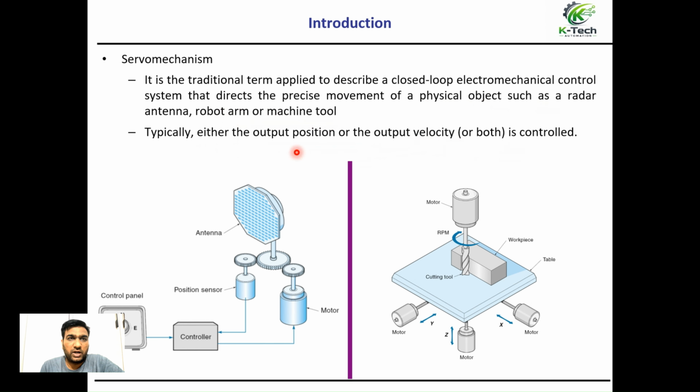A servo mechanism is a closed loop system. Whatever you control, whether speed control, position control or torque control, the feedback is required. The same thing you can achieve in a drive also. The latest VFDs also offer torque control, position control, and speed control.